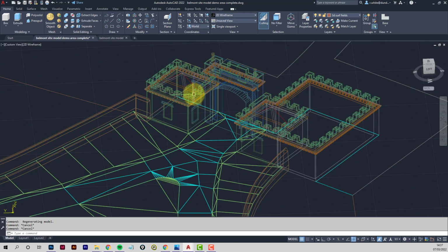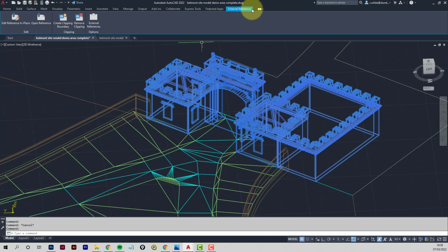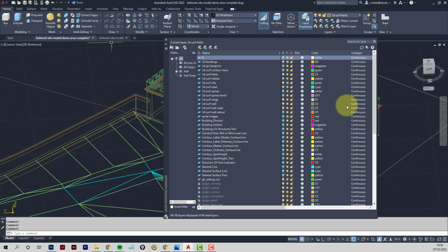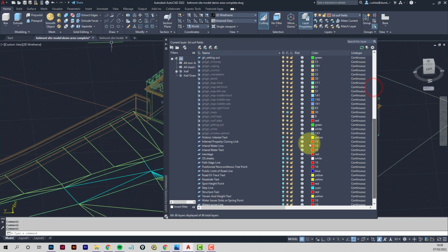Okay, you notice this is greyed out because this is an XREF. This isn't actually in this drawing. I can't do much with this file. As I click it, you see it says it's an external reference. If you look at the layers list, you eventually see these ones that are greyed out. These are part of the XREF. So it has the file name first, the GH, that's gatehouse, and then this vertical line symbol is called pipe, and that just separates the parts of the name for you.